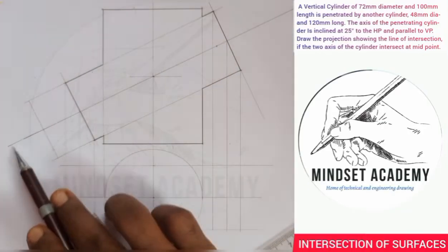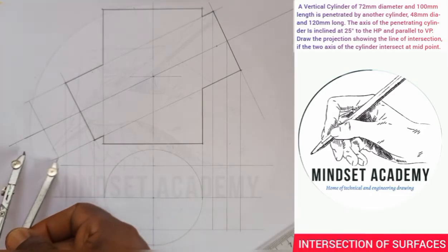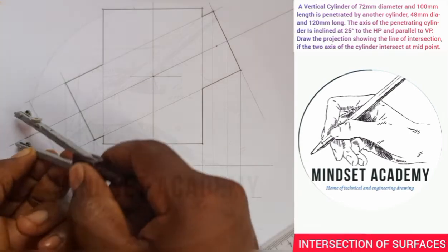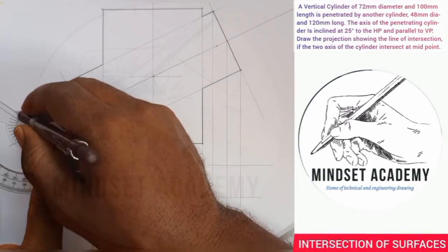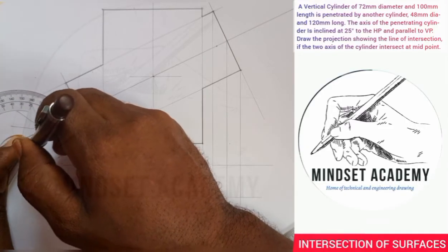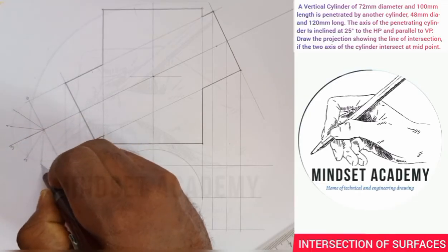You can see that? Now this semicircle here, I'm going to divide it into 6. How will I do that? The same radius that I used to get from here to here, I'll place it here. I'll strike an arc up. I'll place the other point to here. I'll strike an arc down. Then I'll place it at the center point here. I'll strike down and up. So where those points meet, I'm going to take it towards the center this way. This way. You can see, so I can call it 0, 1, 2, 3, 2, 1, 0.